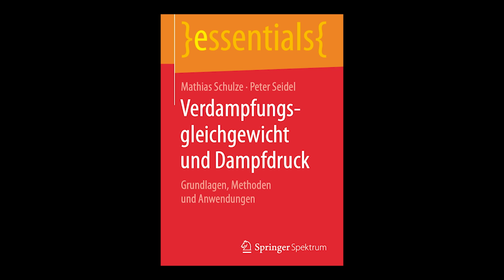Exactly. It often utilizes the solid-liquid phase transition as it's easier to contain than the liquid-gas one. Materials known as phase change materials, or PCMs, absorb a vast amount of heat when they melt, often at a very specific, useful operating temperature. And then when they re-solidify, they release that stored energy steadily and consistently back into the system. It's a way to hoard energy at a constant temperature, like those great little hand warmers we all used as kids that you click to turn hot.